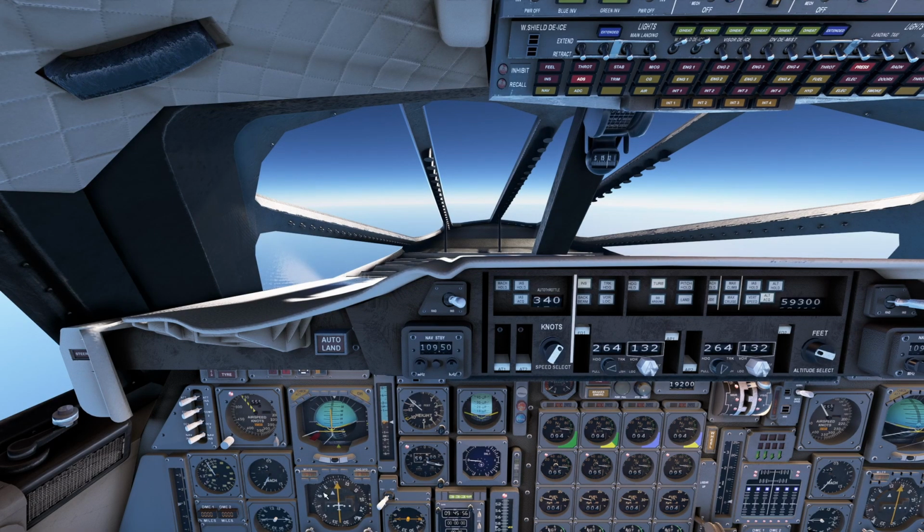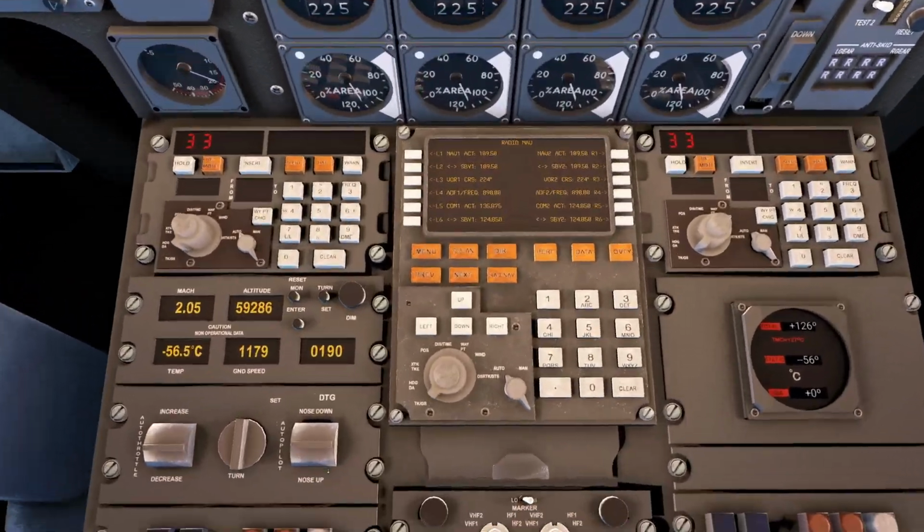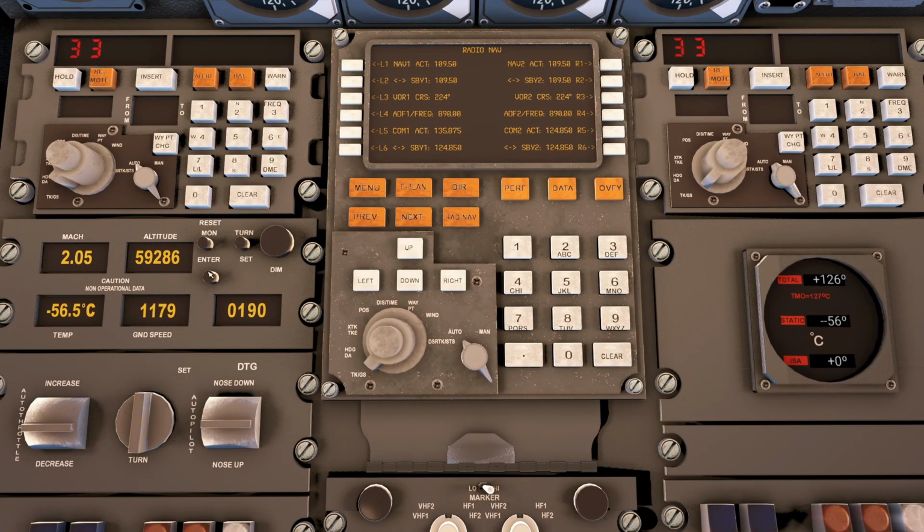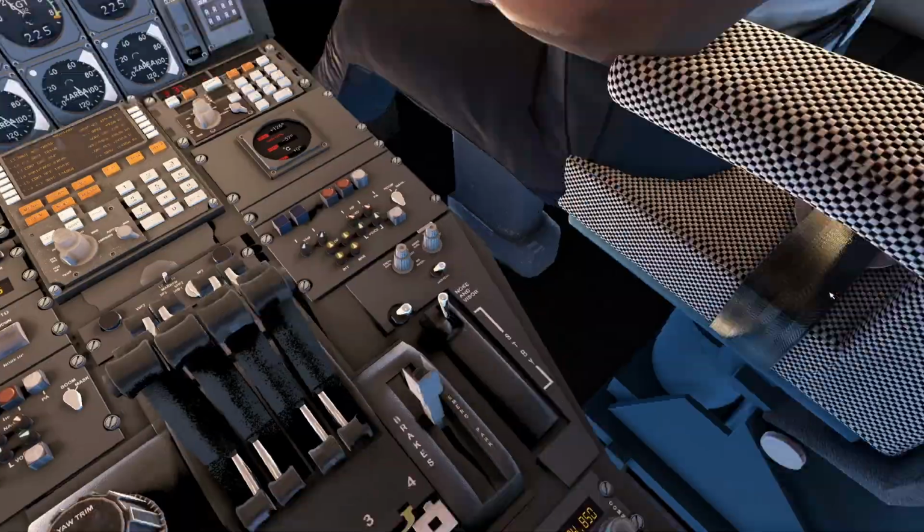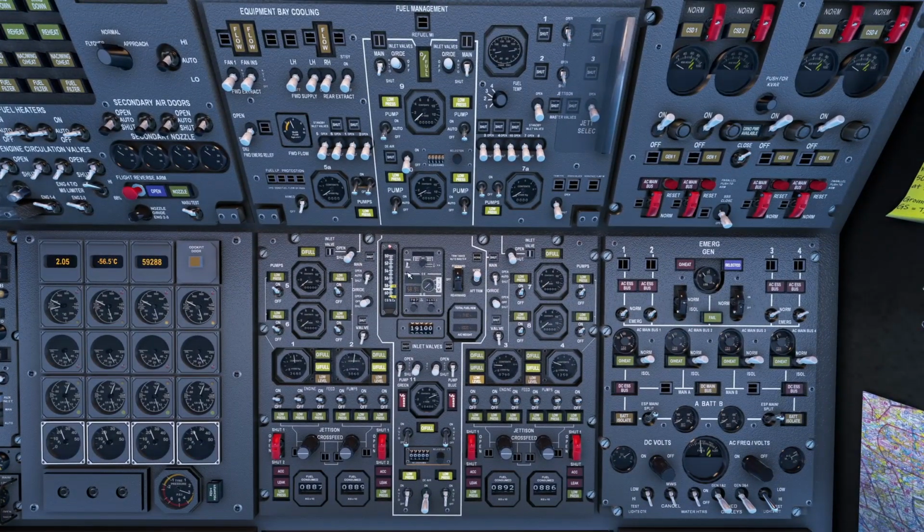Rapidly approaching our point of descent. Concorde made it to almost 60,000 feet. We're at 59,300, stable at 2.04, right at the edge of the temperature. Our trim is still good. Fuel situation has gotten worse, but we are gonna descend soon and are not gonna use too much fuel again. For an alternate, the situation would become problematic.